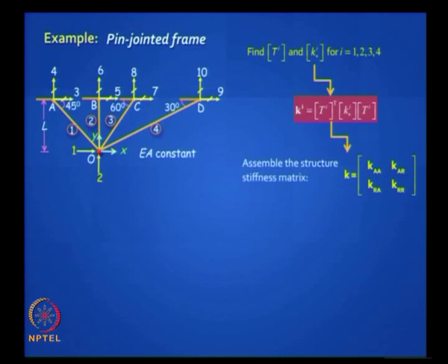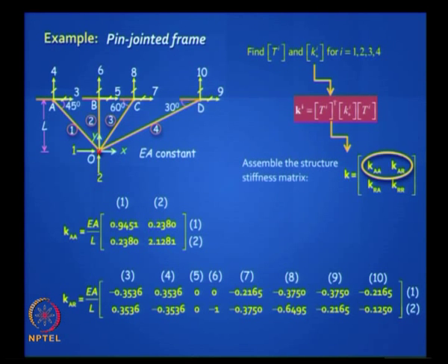So mind you, up to this stage you are dealing with the property of the structure and you say now give me the loads, I can handle it, but the computer does this in a jiffy the moment you feed in the geometry of the structure and the material properties. It is ready to handle any loading because it is already going to work out these properties effortlessly if your programming is good. For example, in this structure you do it this way. Let us look at Ka, it will be a 2 by 2 matrix because you have only 2 active degrees of freedom, and Kar for example would look like this. But in this method you have to always keep track of the linking global coordinates which I have shown here.